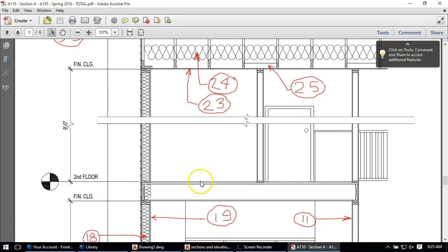It doesn't say, but I'm going to make it the same 3/4 inch because that's what it looks like here. If it's a wood floor, it could be 3/4. It could be thinner if it's a composite thing. It could be thicker if it's really solid wood. Obviously, if it were carpet or something else, it'd be something different entirely. But we'll go with just 3/4 inch for that. So I have to construct this whole area to begin to find where my second floor is in the first place, since it's not really given there.